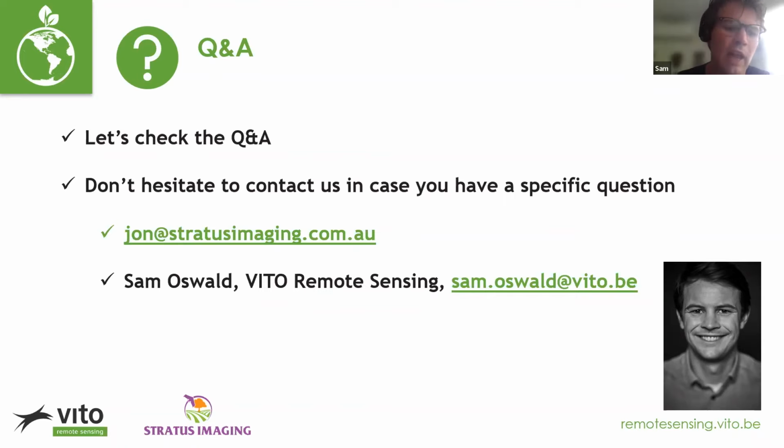So normally you will aim to go for the highest possible resolution, but this is constrained by the camera you're using. So for things like the Phantom 4 RGB, it's going to start getting more difficult to get good quality data if you go at finer resolution than 5 millimeters. And if you're looking at a larger site, maybe it's not going to be feasible to capture all of the data in time.